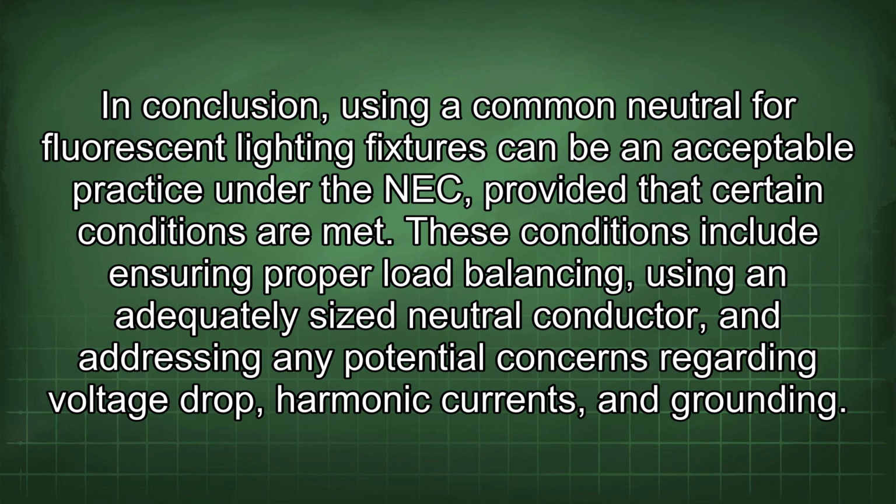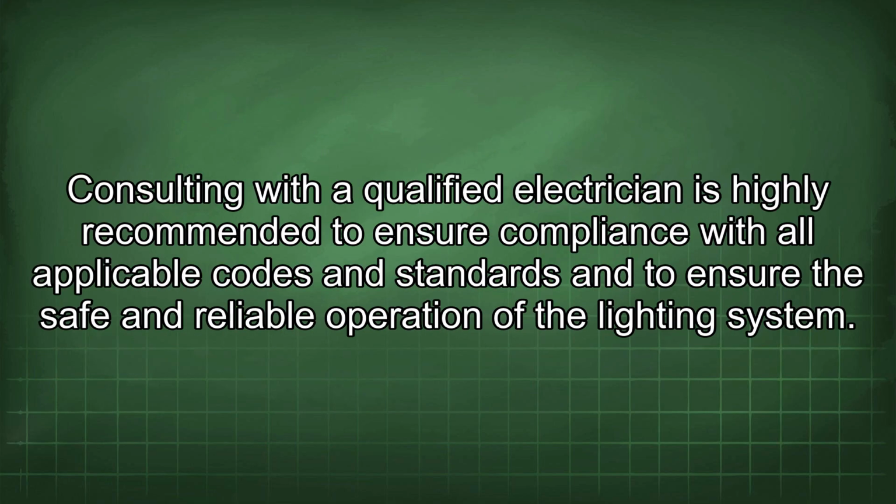In conclusion, using a common neutral for fluorescent lighting fixtures can be an acceptable practice under the NEC, provided that certain conditions are met. These conditions include ensuring proper load balancing, using an adequately sized neutral conductor, and addressing any potential concerns regarding voltage drop, harmonic currents, and grounding. Consulting with a qualified electrician is highly recommended to ensure compliance with all applicable codes and standards and to ensure the safe and reliable operation of the lighting system.